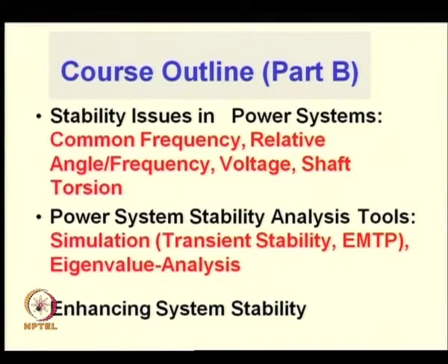Okay. We also actually merged, we did not consider this as a separate topic, although I had listed it as one. We have in fact done a few simulations, and there are two kinds of simulations we did. One in which we considered network transients and stator flux transients, and the other in which we did not. The studies in which we do not consider network transients and stator flux transients are called transient stability programs, because these are rather suited for the study of low frequency phenomena. And EMTP kind of programs in fact have to model fast transients in detail.